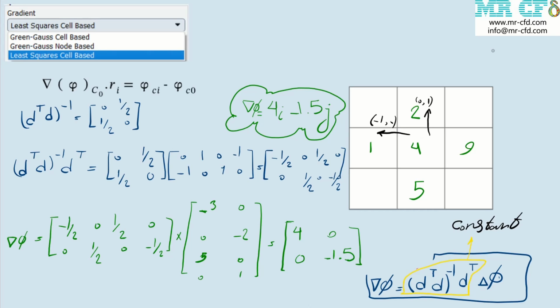On irregular, skewed and distorted, unstructured meshes, the accuracy of the least squares gradient method is comparable to that of the node-based gradient, and both are much superior compared to the cell-based gradient. However, it is less expensive to compute the least squares gradient than the node-based gradient.